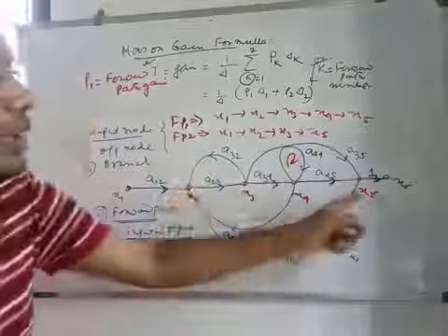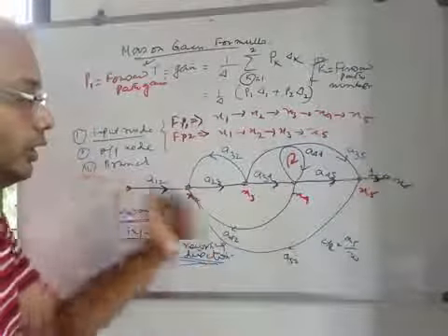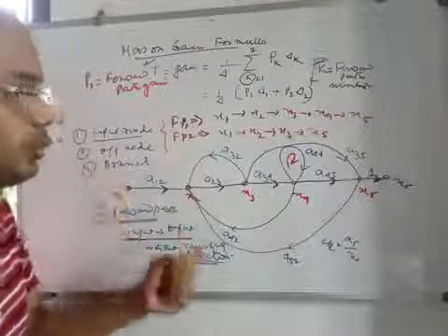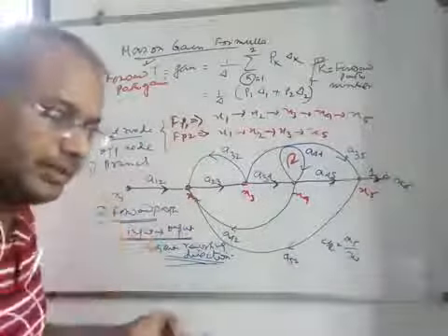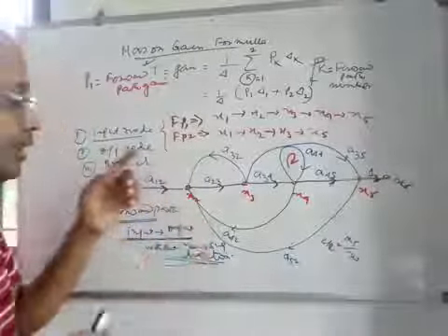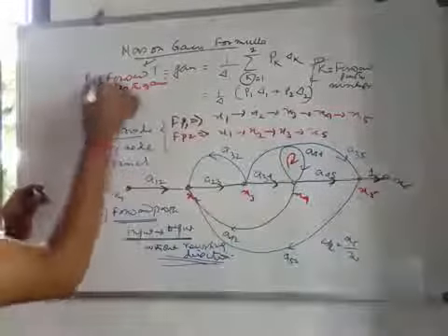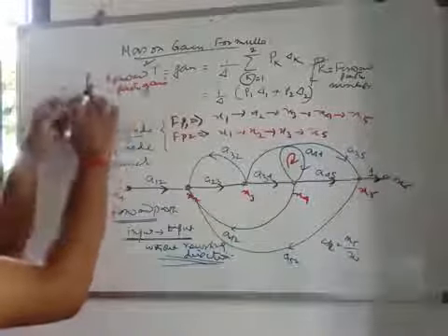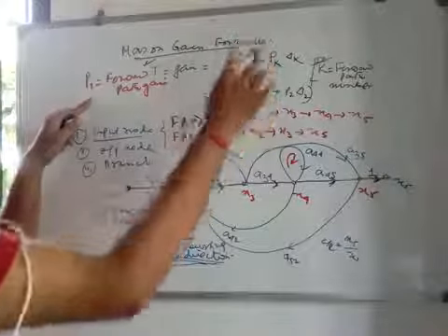So this is the path gain for that forward path 1, right? So in order to move from input to output, there may be different forward paths, and once a forward path is chosen, there are different branches through which it has to move. So the branch gains will be multiplied. So p1 is the first forward path gain, k equal to 1 means first forward path, k equal to 2 means second forward path.